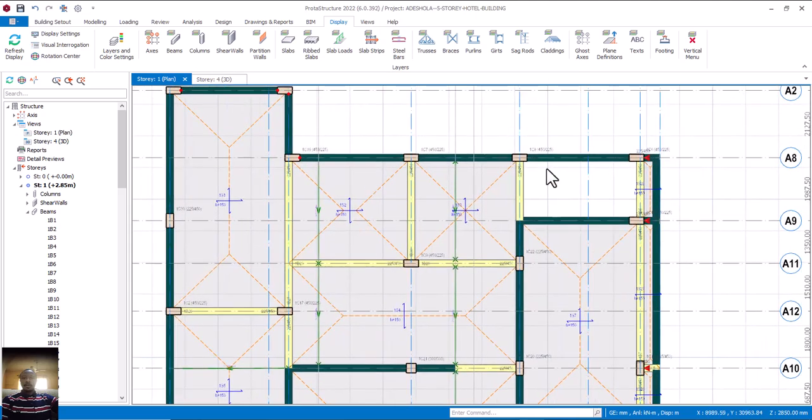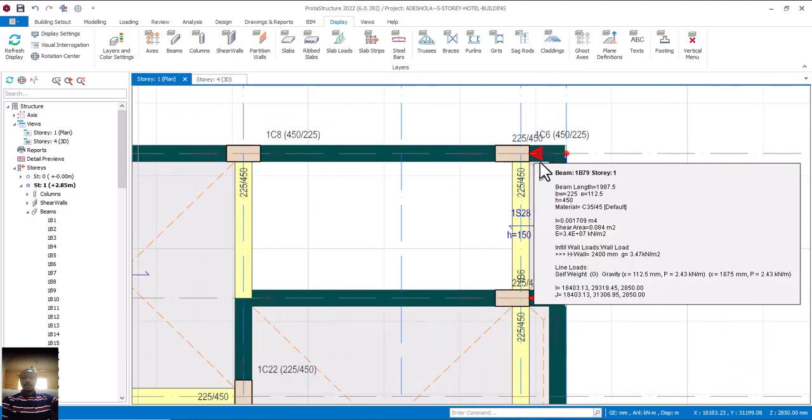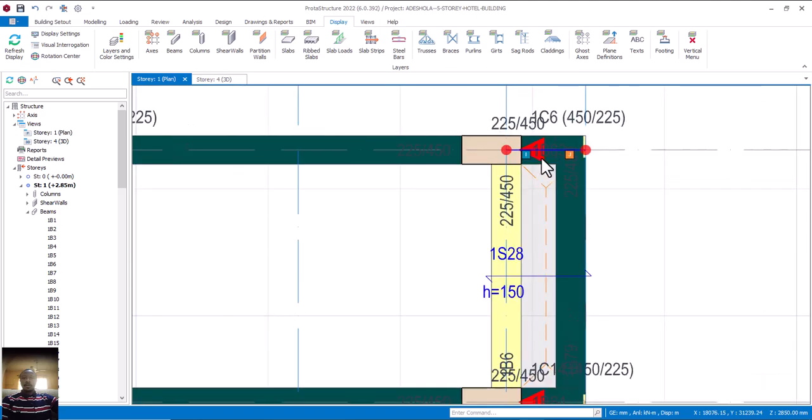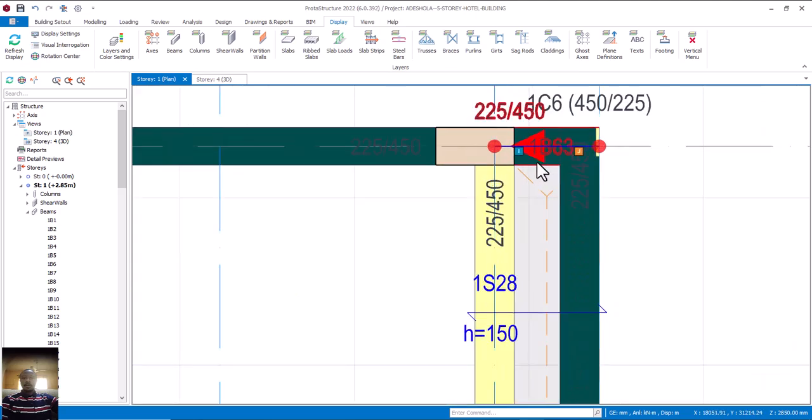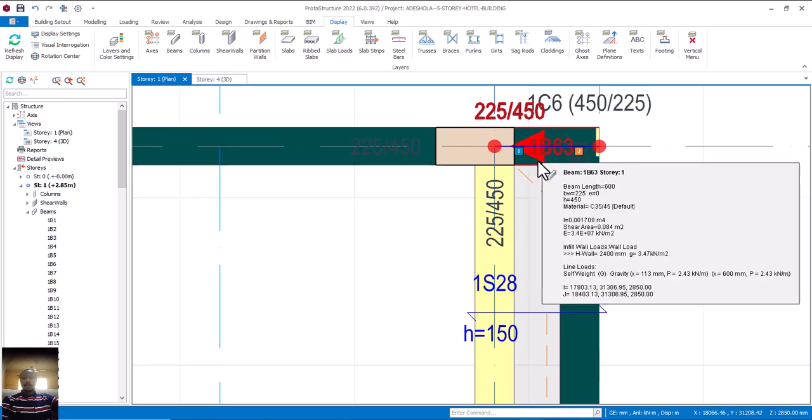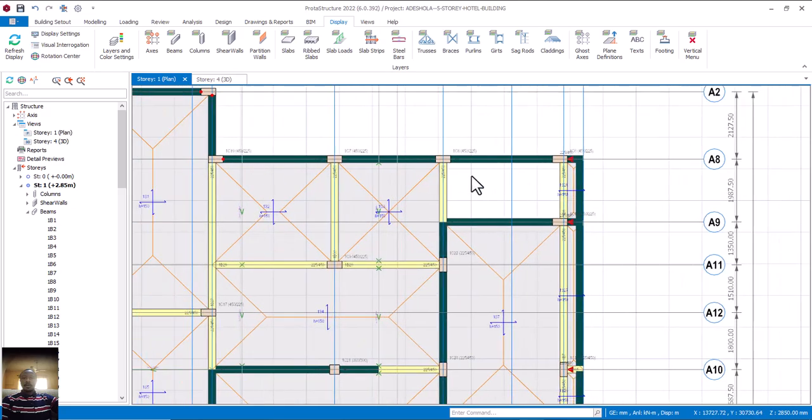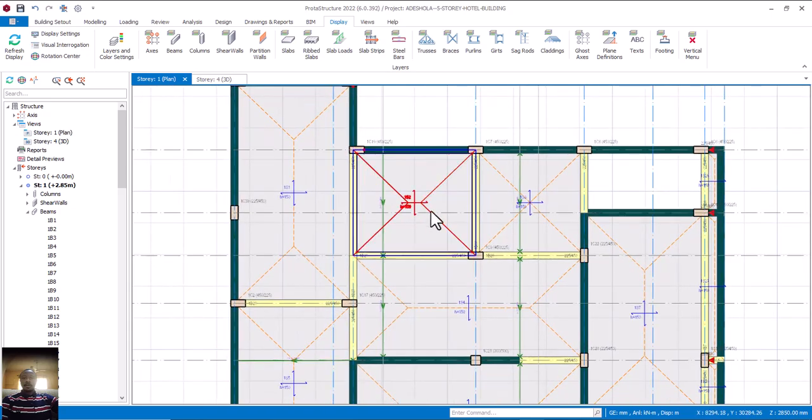So now I come along this side. Okay, now don't go and make the mistake of hinging this place, because this is a cantilever. If you hinge this place, automatically it will fail in the course of construction. So you don't hinge this place. Let me just deal with horizontal first. Horizontal first.